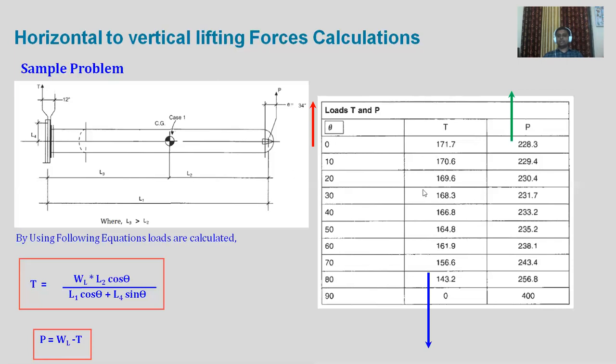At various angles we should calculate, but if we don't want to calculate the stresses at every angle, what we can do is take the worst from this, and the worst from this, which will never actually appear. But for the sake of calculation we are taking the most conservative values in both the conditions, and if it is safe in that conservative condition, then we can say it will be safe in all other conditions.